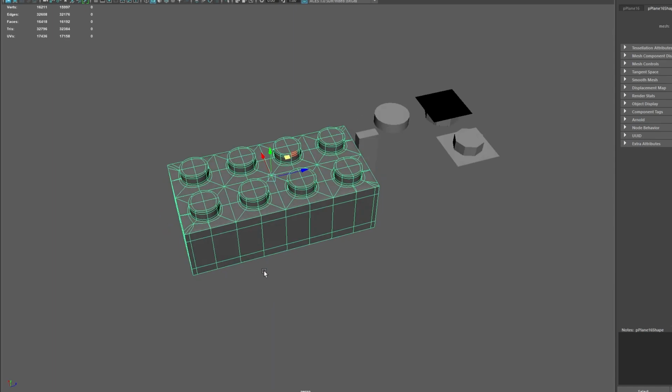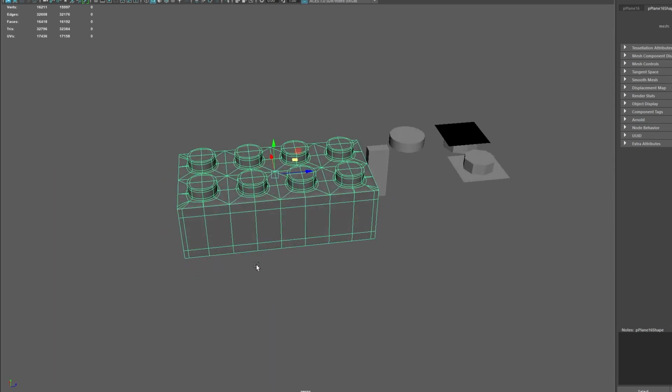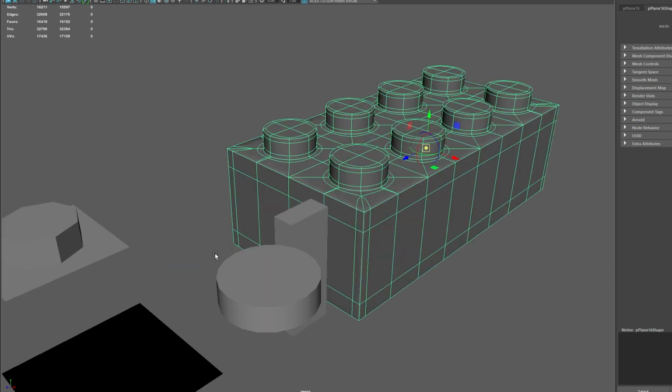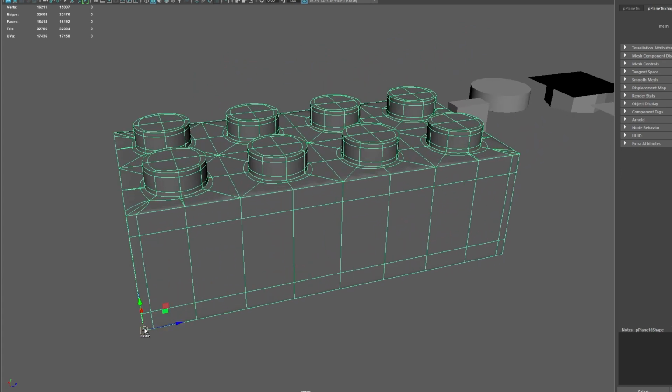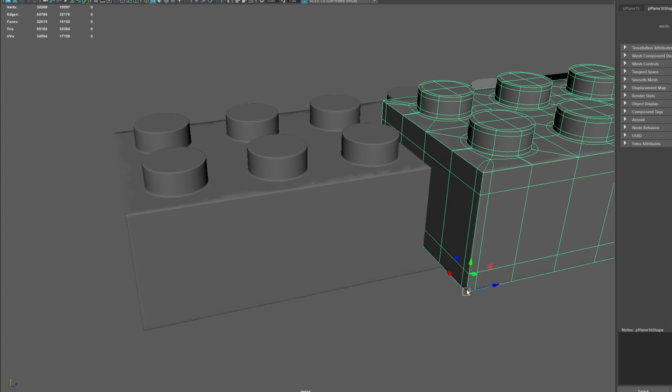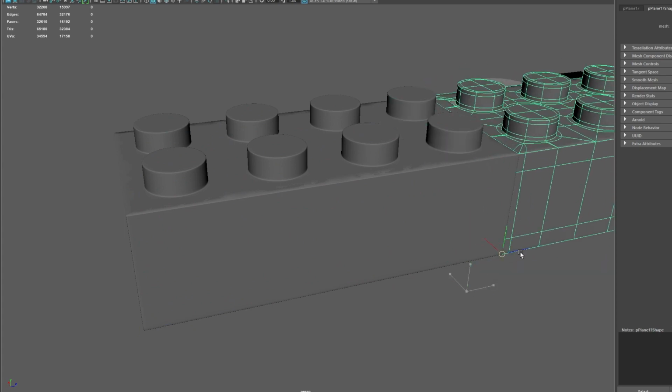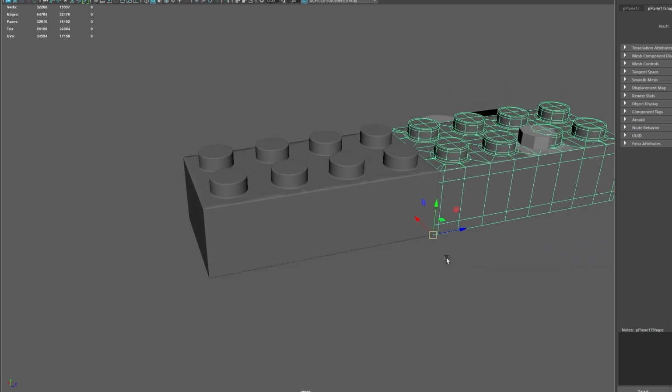Now, to stack blocks together, I would find it easier if I hit insert and move the align points by holding V down to this corner here and then hit insert again. Now if I want to clone this, I can simply hold shift down, grab this corner, and snap it accordingly.